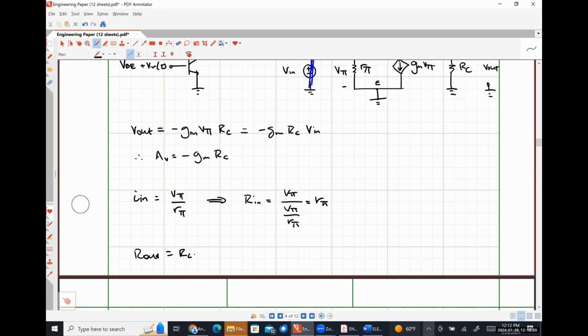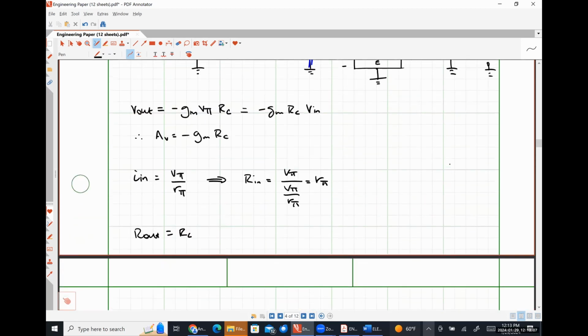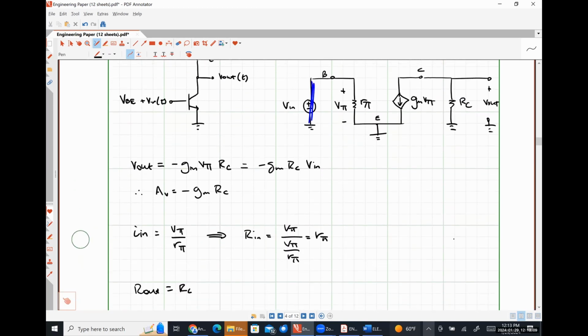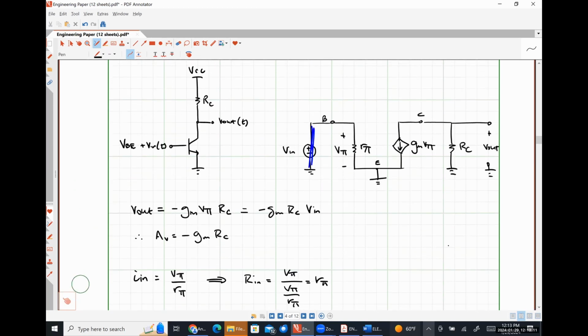We just analyzed our first transistor amplifier circuit. The easiest possible one to do, to be very, very clear, but we just analyzed our first one. So now let's throw you guys a curveball because we've got 2 minutes left. Let's say that this was a MOSFET. What would the only difference in our small signal model be? This would be an open circuit now. Everything else would be exactly the same.